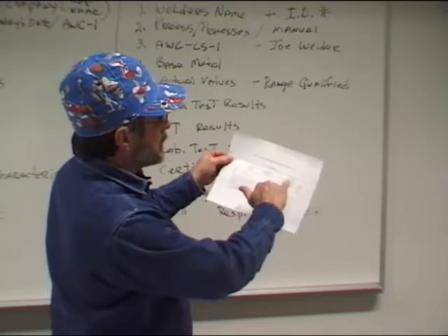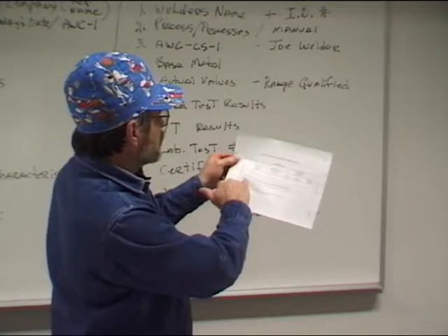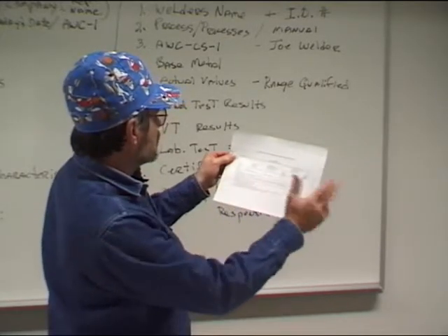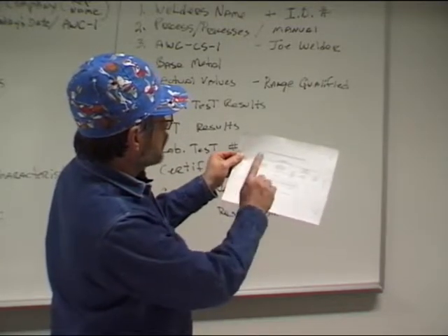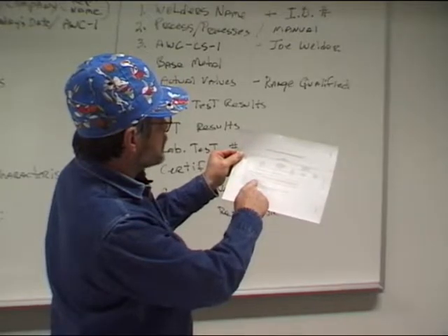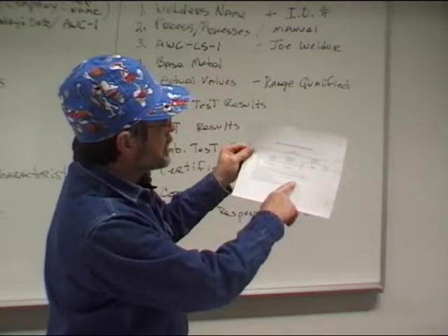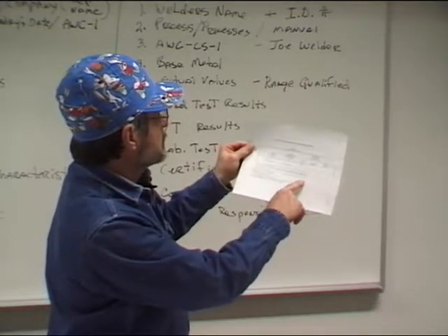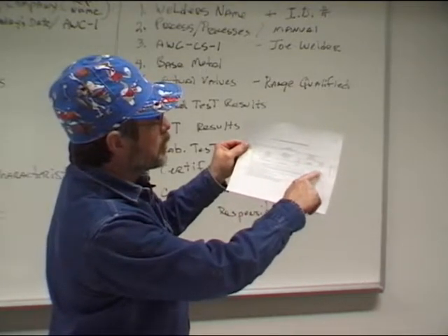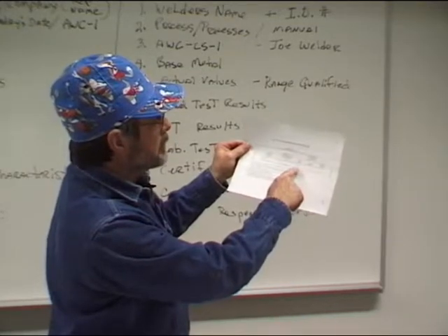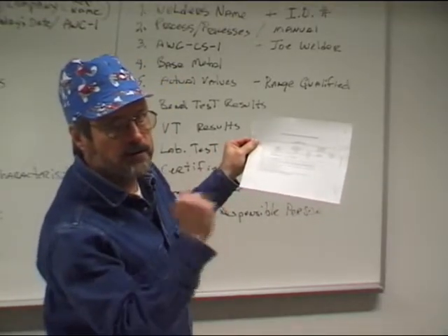And let's see, under type and number of tests required, it says see notes 3, 4, and 5, so you're going to read those. It says 2 or more pipe test coupons of different thicknesses may be used, and so on. Note number 4 says to qualify for positions 5G and 6G as prescribed in QW 302.3, 2 root and 2 face bend specimens or 4 side bend specimens as applicable to the test coupon are required. So even though it says 1 and 1, once you read note 8 over here, once you read note 4, it tells us, well, we really got to take 2. So you're doing 2 face bends and 2 root bends.